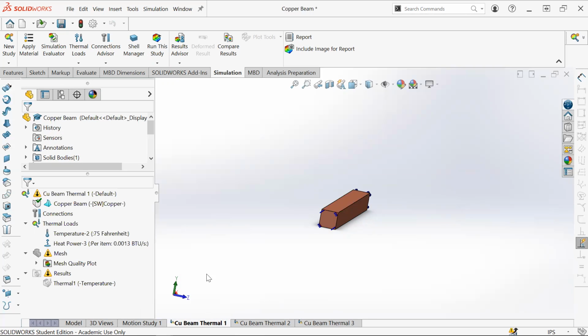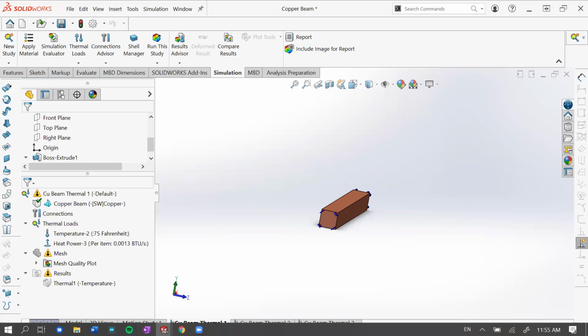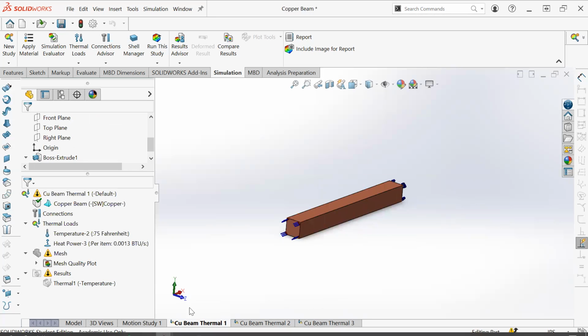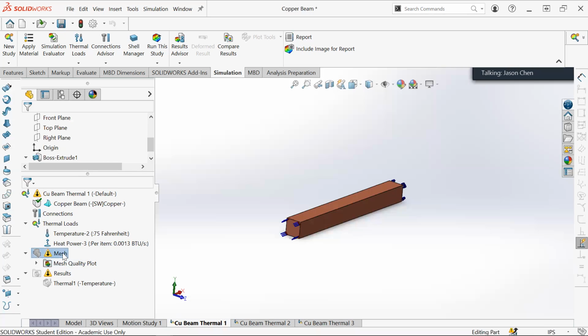In this case, I started with a model, I did a study, changed the model, started a new study, finished the study, changed the model again, and did the 3rd study. And thus the model ended up with the 3rd simulation's model. So only the 3rd simulation's model matches the current model I had previously before I changed it. So now I changed it back to model 1, simulation 1's model, and now I can remesh. Unfortunate, but what can you do?